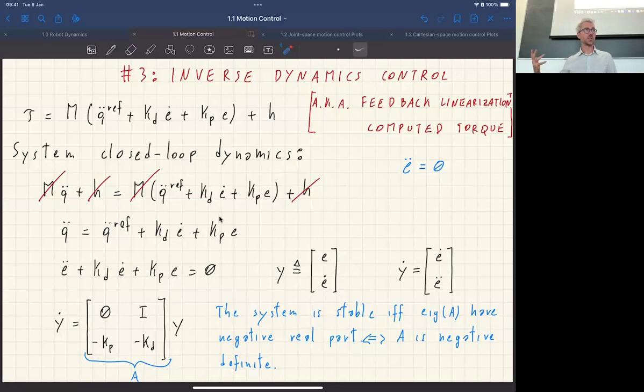These are all quantities that depend on the inertia tensors of the links of the robot, which is a bit tricky to identify. Whereas gravity only depends on the masses of the links, which typically you know quite well, and the centers of mass of the links, which again are easier to identify than the inertia tensors.